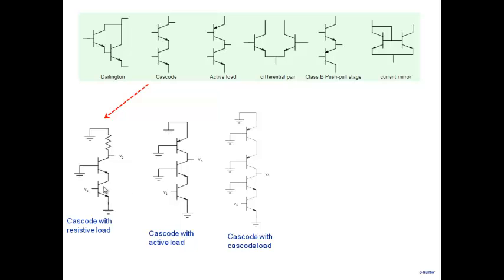It says, note that for cascode, all that you're looking for is that this drive transistor should not see a high load here. Why? Because at this point is where there is collector-base capacitance which is getting multiplied by Miller's effect. So at this point, it should see a low resistance. That's the aim of the cascode. Low resistance here. And the place where you're building the gain, that's where you should create high resistance. High output resistance here. Alright. So if we can do that, not just with an NPN.